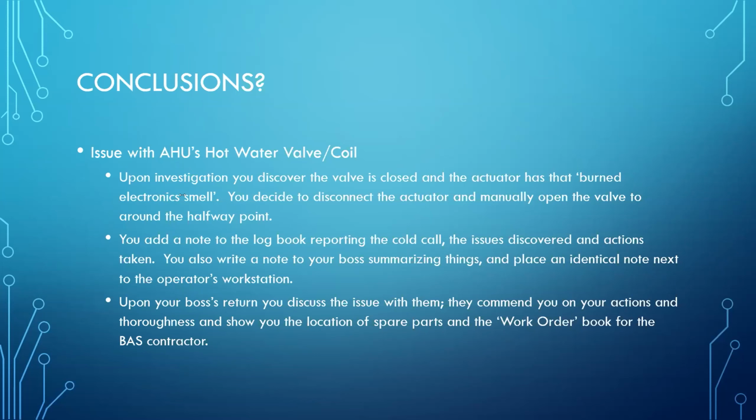So our conclusions, and I know we went through this last bit a bit fast. So we have an issue with our air handler hot water valve. So obviously we have to follow up on this. So we went and we investigated. We looked at the valve because we can get to there versus the VAV, and we found that the actuator has that characteristic burned smell to it. So we have a bad actuator.